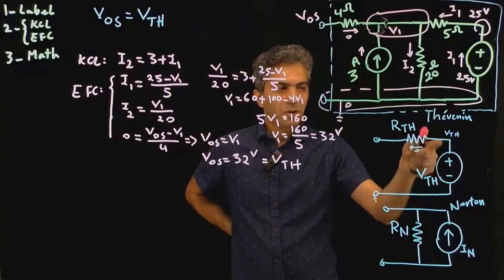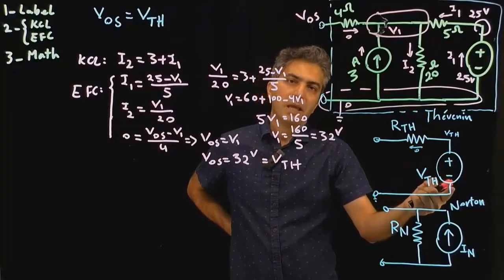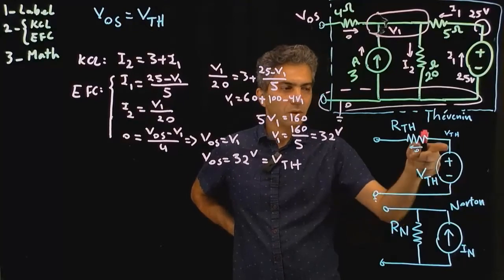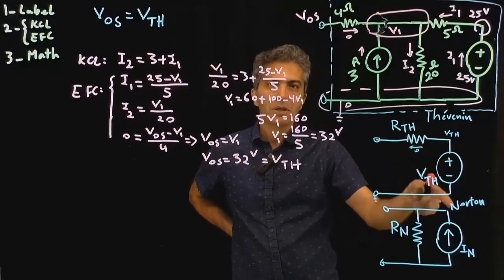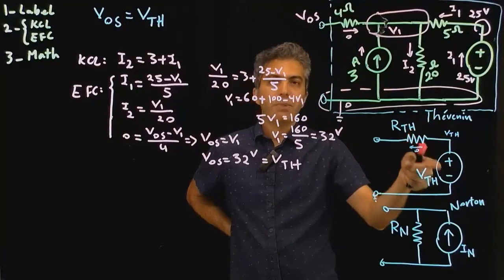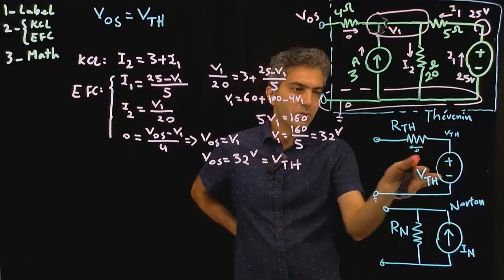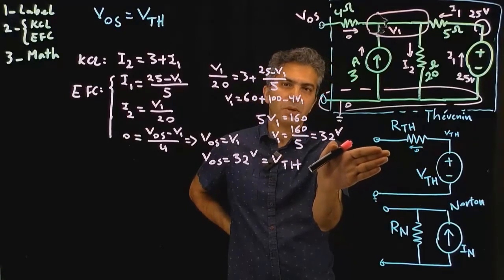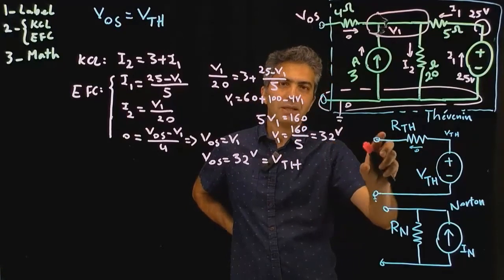When voltage across two nodes is 0, that means the two nodes are shorted to each other. So by turning off a voltage source, I am actually shorting out the two ends of any independent voltage source in the circuit.